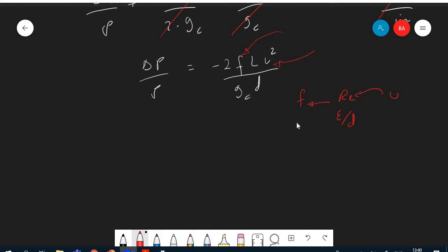But if you look at that for a moment, all I want to get at the end is Qm, right? I want to get Qm. And to get Qm, what I need is the velocity u multiplied by rho and A. So if I can get u, and I already have the density and area, I can get the mass flow rate at that broken end. But how do I get u if I don't have delta P?